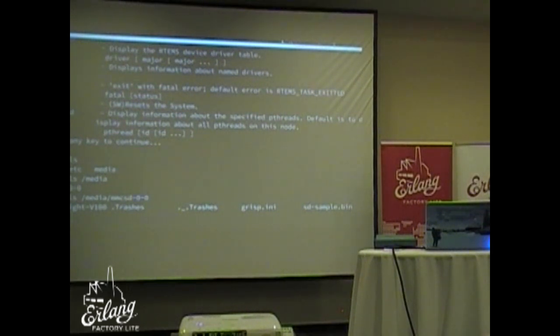Yeah, yes, I understand, but why do people want to choose this board? I mean, between Raspberry Pi and this? So I would say the main argument is the connectors. You have easier, more low-level hardware access to different connectors, and you can plug and play these PMODs and stuff like this. It's a bit more work to do that on a Raspberry Pi or a Beagle board. And also, if you don't do anything special, you have Linux and you have to find drivers. Here we want to provide everything out of the box, already built in. So that's the ease of use also.